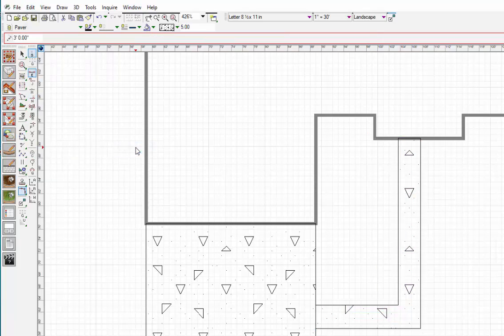Okay, and then with the trim round tool, what it does is it gives me the ability to set a radius for the rounding there. So if I want that to be, say, a 4-foot radius, I'll change it there. I'll click on this line here and then this line here, and what that does is it gives me a radius there.